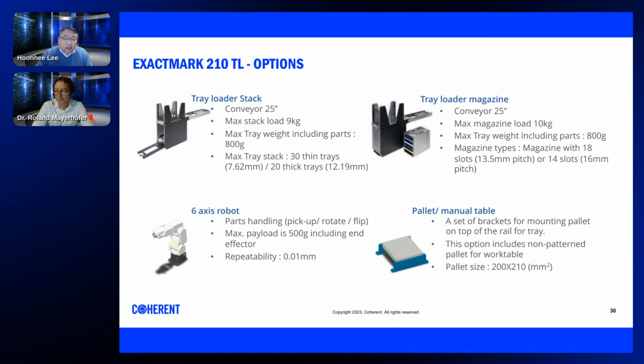ExactMark 210TL comes with three main options. Tray loader, which you could select as either stack type or magazine type. If your parts are less than 10 millimeter, you could use a stack type to maximize the MTBA. Though if your parts are taller, then you could use magazine type, which allows you to use up to 40 millimeter parts.